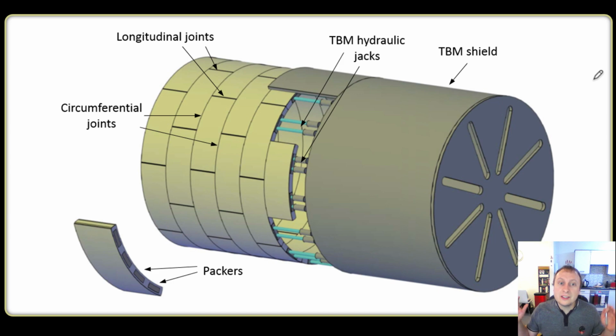Okay, so here is our standard setup. This is rectangular segments. As you can see, it's a nice straight line, but if you were going around a corner, there are a few ring beams here. So for example, let's take this one. That ring beam could be packed out on the left-hand side, and it's like a salami: you can cut it in a certain way and then lay it out so that you get a curve. So this particular system works brilliantly on corners and always has, and there are very good reasons for that. It doesn't really make much sense to me to go away from a system that already works really well on corners.